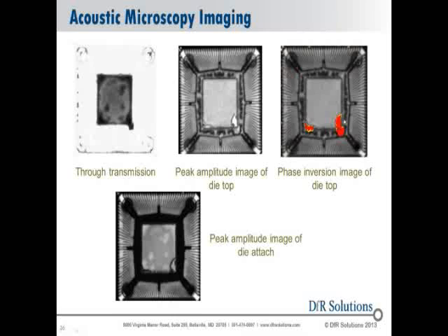In this case, the red one that lights up is telling you that there are some voids and air gaps going through on this part, or the one that's solid on the phase through is telling you that it's intact, which is why it's transmitting the signal all the way through. So these become a little specialty on how to read and interpret these, similar to how a medical doctor reads an X-ray.